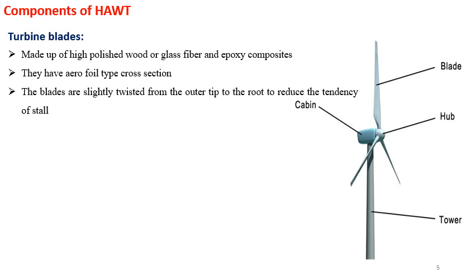It is not best suited for electric generation, which requires very high rotational speed, in terms of several thousand rpm. The reverse is generally true for lift devices. Small rotors can often rotate at such speeds and can be connected directly to the generator, while larger rotors require step up gearing.